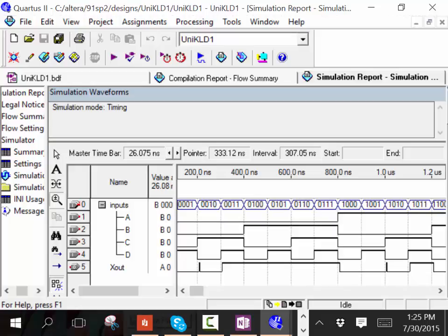So if I turn those two off right there, and I turn on, say, for example, 1011, the LED comes on. So I'm actually seeing the design that I built in the schematic show up on my board right there. So this is the way we typically do digital logic today. The old way would be to hook up the chips and wire the pins. Now we do it internally.